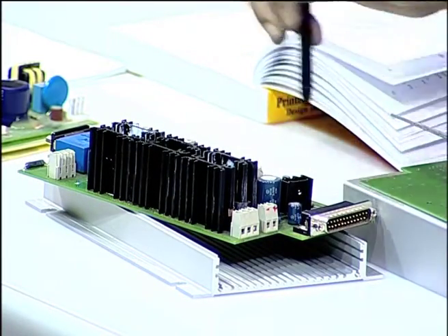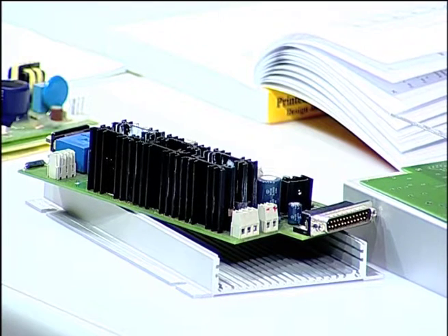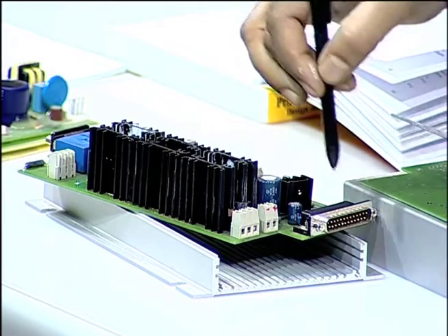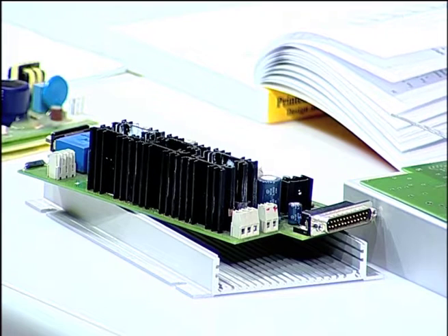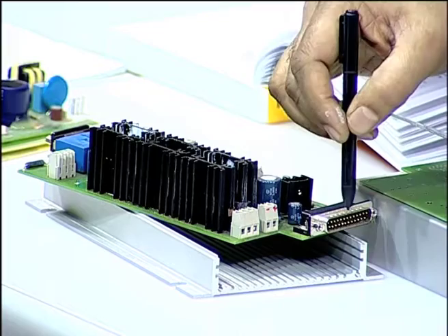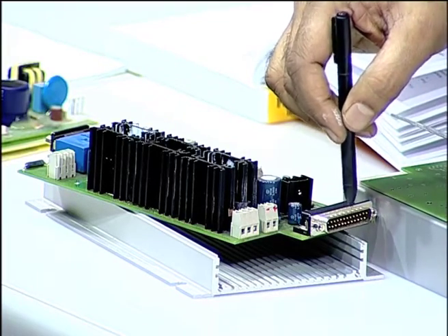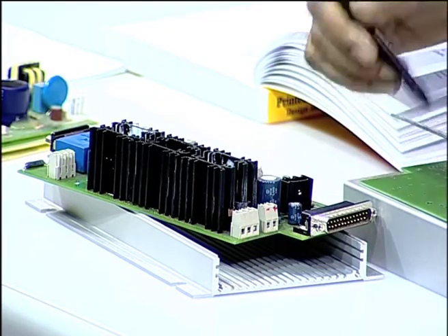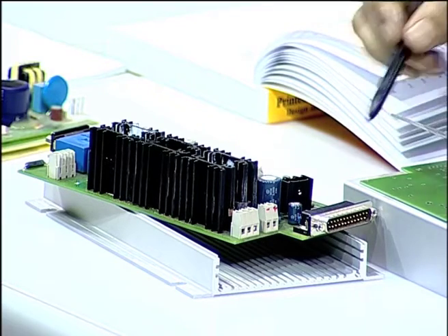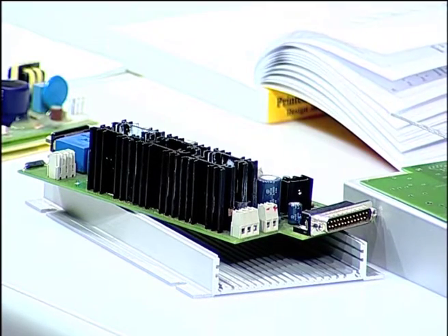So these occupy quite some amount of space in your printed wiring board, and these are the external links from the PCB, or this is where the internal circuit gets linked to the external world. So, the connectors should be placed according to how the external links, or where it connects, is decided. This is where some amount of discussion with the physical equipment designer also matters a lot.